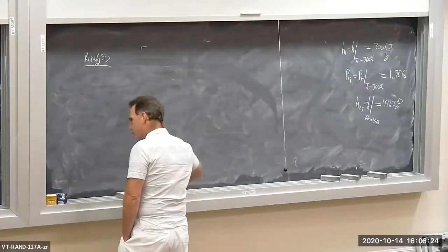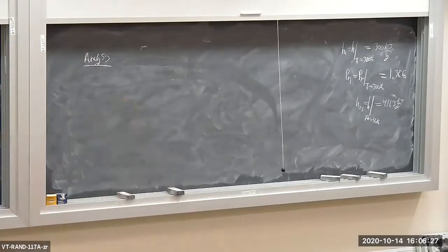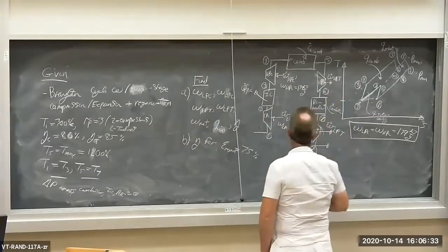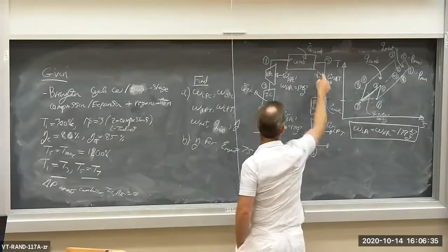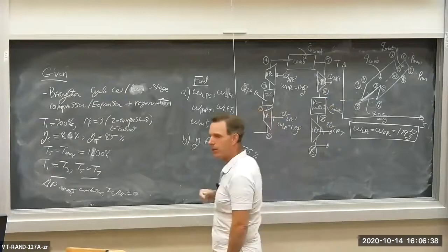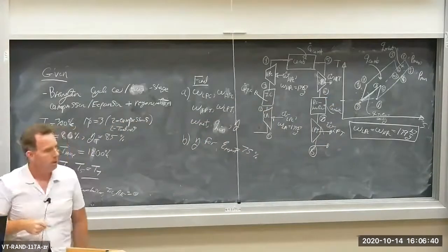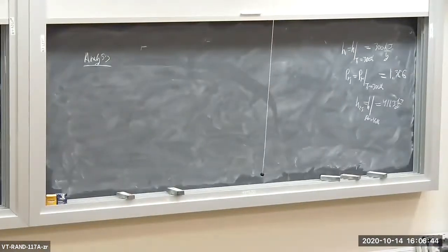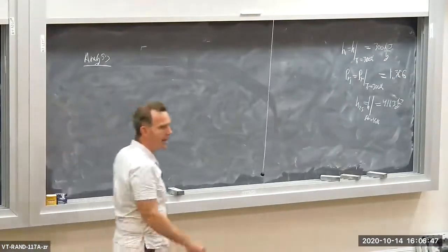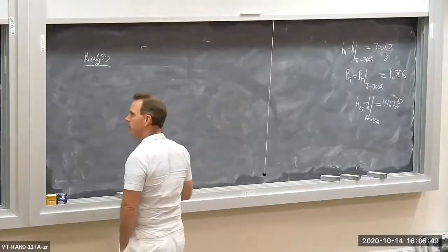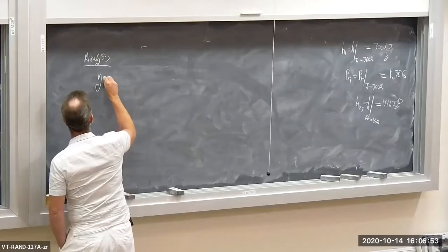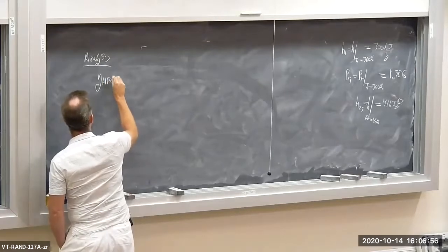So the high pressure turbine, expansion process on the high pressure turbine occurs from state 5 to state 6. I know the temperature at T5. I don't know anything about state 6. I don't have a temperature. We're running into the same problem here. If I try to apply the energy balance from process 5 to 6, I don't know H6. So I think I better start off with the definition of isentropic efficiency for the high pressure turbine.